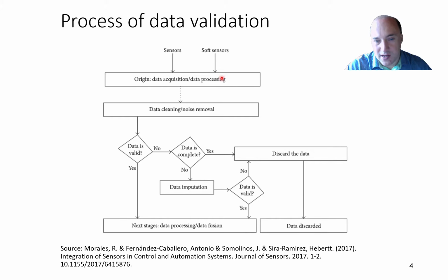Regardless of the origin of the data, we need to process the data somehow. So we then typically take this data and we clean it or we remove the noise. So we may use here, for example, some low pass filter or some high pass filter, notch filters, for example. And the purpose of this block is to clean the data of what we do not want in the process. For example, if we measure temperature, then we know that the temperature changes due to heat capacity can be relatively slow, so we can remove all high frequency data. And we will not focus on those algorithms. This is for a probably different class. I think you already had or you will maybe have some class about filtering, at least some lectures.